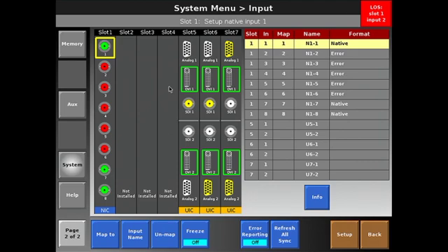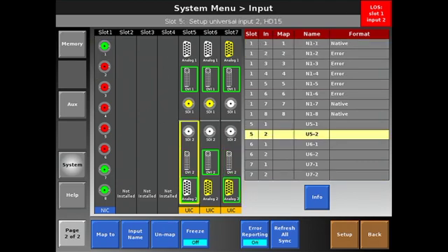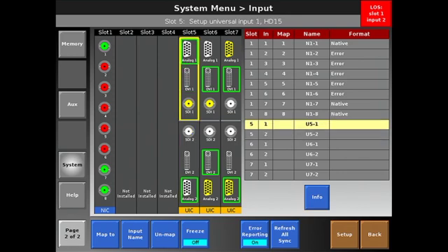On our universal input cards, we have the ability to bring in analog or VGA inputs. Also in the analog connector, you can bring in composite, component, all of your analog video sources. DVI sources for standard DVI video, as well as SDI if you have something that's not running 720p, maybe a 480i camera or a 1080i camera. Those can come into the scalar card as well and be converted to the system native resolution.